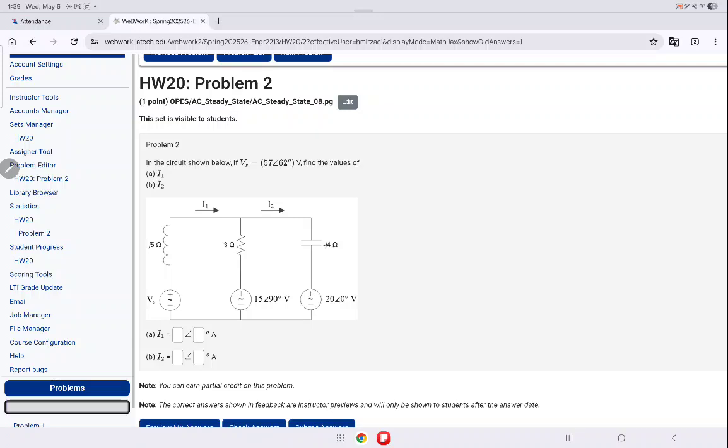The bottom node can be ground. The top node can be your unknown. How about those middle nodes between the elements and the voltage sources? They are all known, right? Because they are connected to a positive part of a voltage source. So one equation, one unknown. Is there any problem?